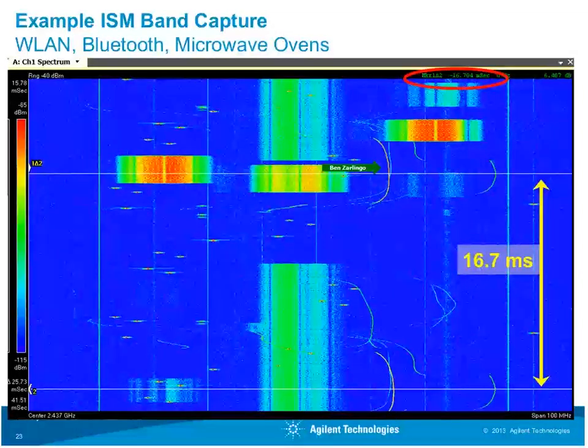And you can imagine with more and more occupants of the band, you could end up with more interference. That interference in some cases can cause receivers to request retransmissions, which then further causes a larger occupancy of the band, and you can imagine how you would reach a kind of cliff effect at some point where interference causes retransmission, which causes more interference, and you end up with a real problem operating the band.